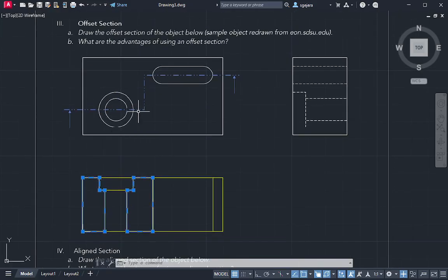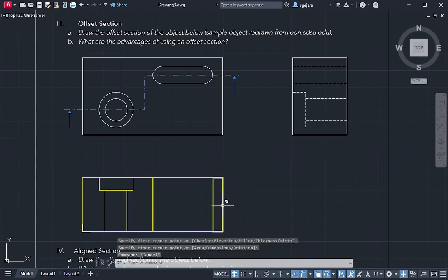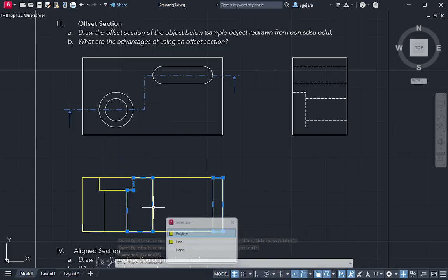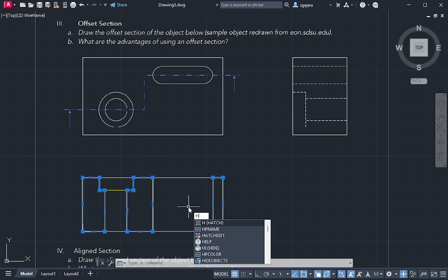Because if you do the sectional view, these are in contact with our section plane, or cutting plane, right? This one is not in contact because it is this surface right here and this surface right here. Okay? And the last one in contact with the surface is actually this rectangle right here. So I can select this and do hatch, H.